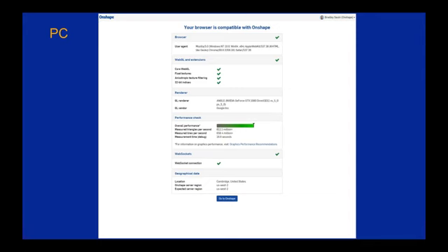When I'm working with customers, I typically see between 20 to 300 million triangles that the computer can process for visualizing the models there. So that's a really good range to aim for if you're trying to see if your computer works well with Onshape, or if you want to double check to see what might be causing some performance issues on your end.